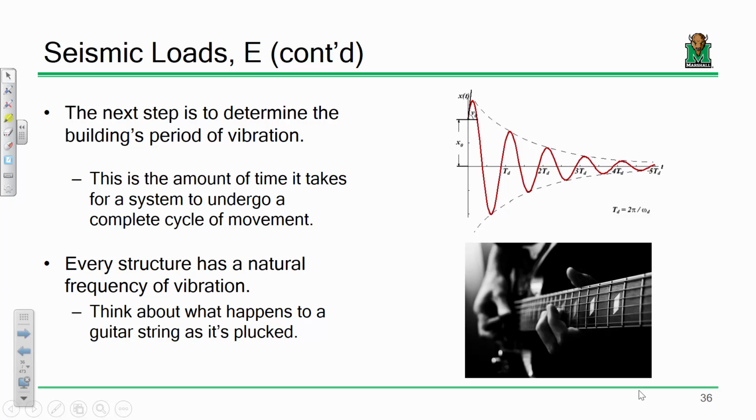Okay. Now, here's the thing. Once structures are undergoing free vibration, it's a fundamental law of structural dynamics that all structures have an inherent natural frequency upon which they vibrate. It's why if you take a guitar string and play it lightly or wail on it, it plays at the same note. Because once your pick leaves the string, it's under free vibration. Does that make sense?